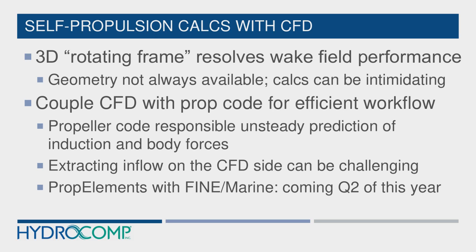So one of the things that's done frequently is to couple CFD with a propeller code like Prop Elements for an efficient workflow. And it's the responsibility of the propeller code for the unsteady prediction of performance, which includes the induced velocities, induction, and the calculation of the body forces that are passed back to the CFD tool.